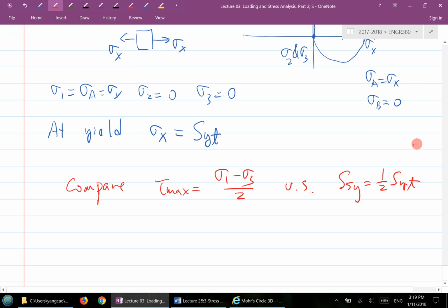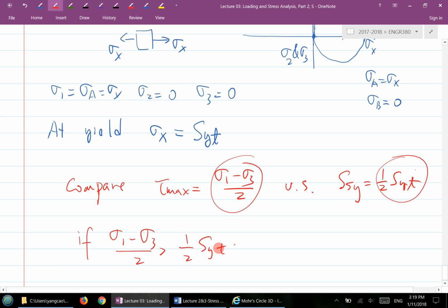And you can substitute this and this together, and you can see that if sigma 1 minus sigma 3 is greater than this, failure. Right? That's basically the idea. We'll look at the details in the next lecture, breaking down into case 1, 2, 3, and we'll draw diagrams trying to look at the safe region and unsafe region. Any questions? Okay, this time is for real.